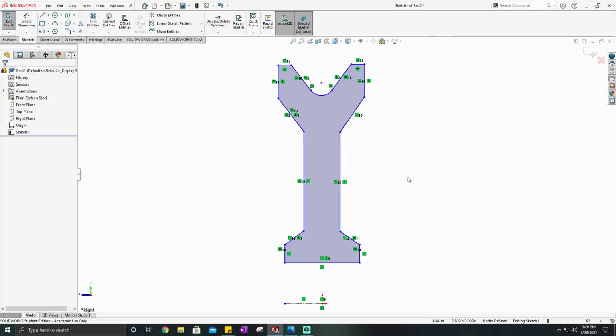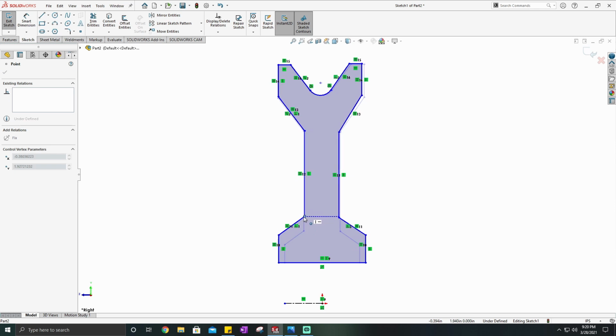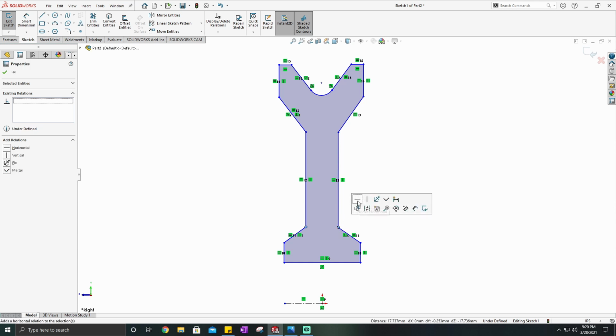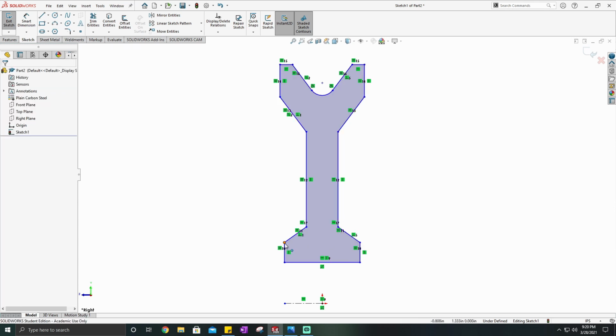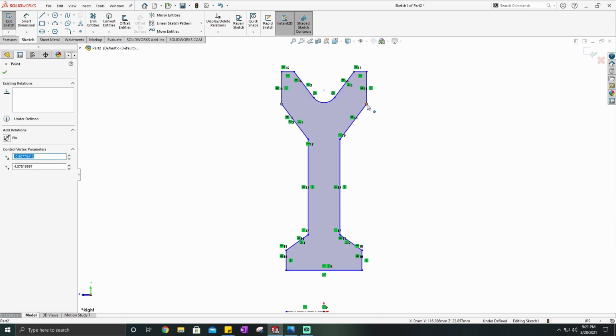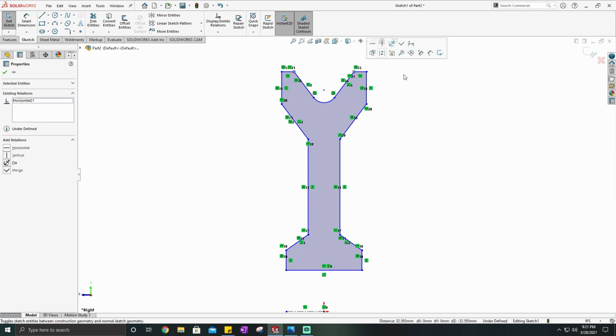Now I can set other constraints to line things up for me. So I know that these two points need to be vertical with each other. I mean horizontal, and so do these. And as you'll notice, if I were to drag one of these up, SolidWorks wants to put them vertical for me, so I can actually just make it so that they stay that way. And I can set these as well, horizontal, make sure these points are horizontally in line, lastly these points horizontally in line, and then make sure this point and this point are horizontally in line.